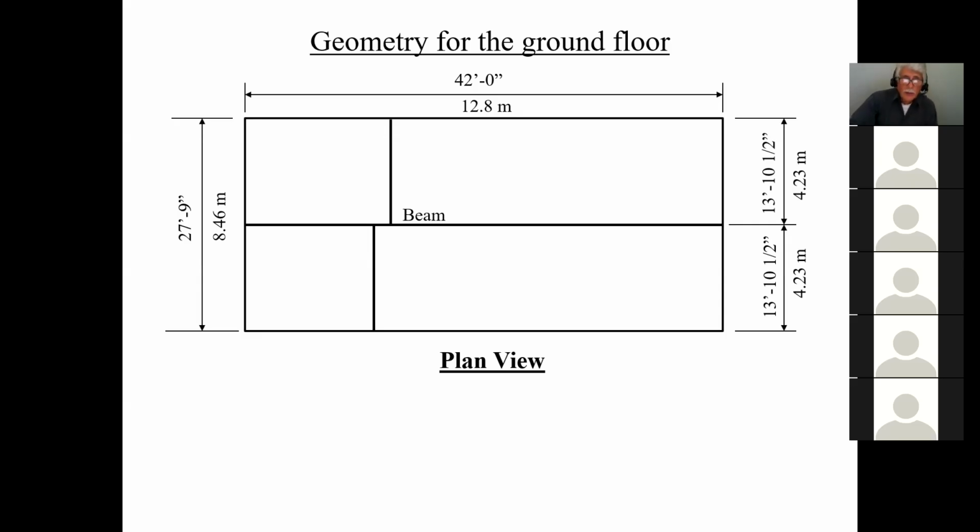Now, when it comes to built-up beams, one thing that you have to keep in mind is that they can carry a lot of load. So therefore, as far as a span goes, you have to limit yourself to around 12 feet, you understand? Even when you start getting up to about 14 feet, it starts being a little excessive for a built-up beam, especially if you want to stay within a 4 to 5 ply configuration. So what I tend to do with a built-up beam is keep a 12 foot span as being probably the maximum span for my beam.